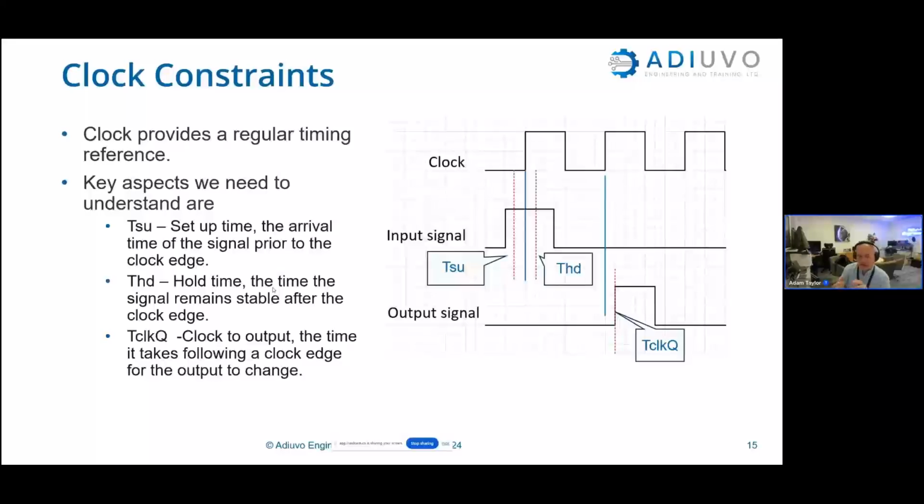So the setup time, the hold time, and the clock to output time become increasingly important in our design analysis and timing analysis, particularly when we're doing I/O type applications. When we're trying to achieve I/O constraints and I/O timing, we really need to pay attention to those. Not that we don't when we're working internally, but internally the tool's going to do a lot of this for us. Externally, we've got to do a little bit more work, with a little bit more concentration with our spreadsheet.